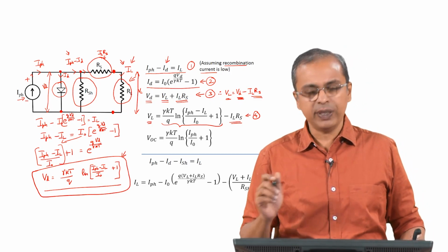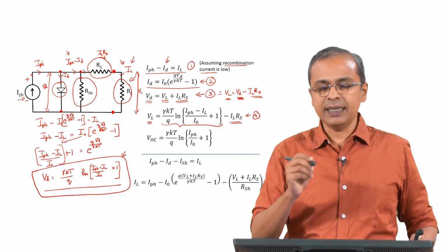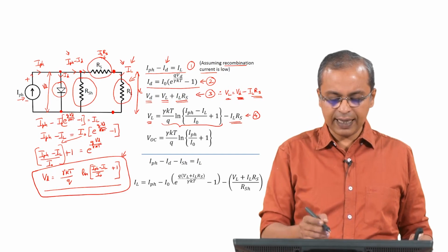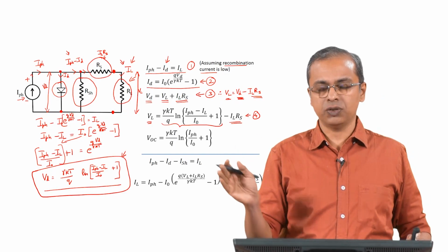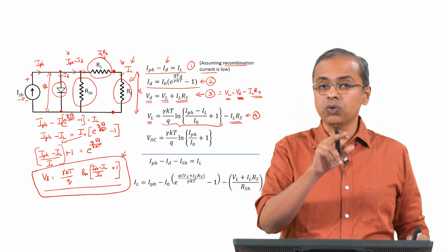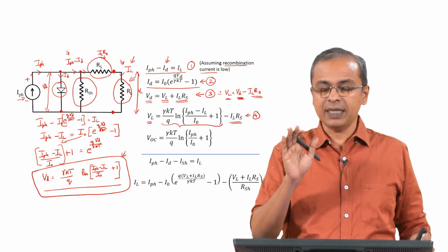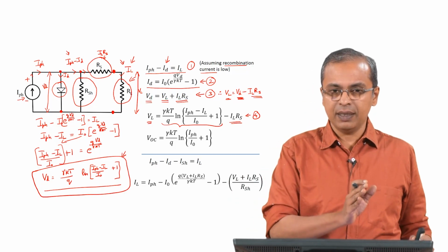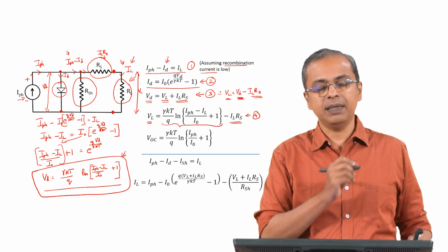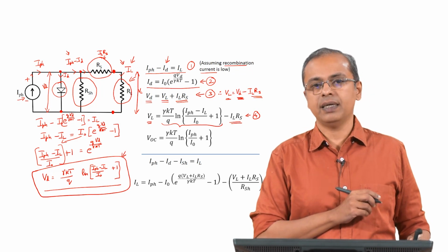So, in this equation 4, if you want to find out the open circuit voltage, the main thing that you have to do is to set the load current to 0. It means there is no load, right. So, you remove this entire RL, so it is open. Since it is open, there is no RL there, the circuit is not complete there. So, there is no question of an IL going into that circuit, because there is nothing there, it is just open. So, if you set IL equal to 0, whatever voltage you get as the voltage across the load will then essentially be the open circuit voltage.